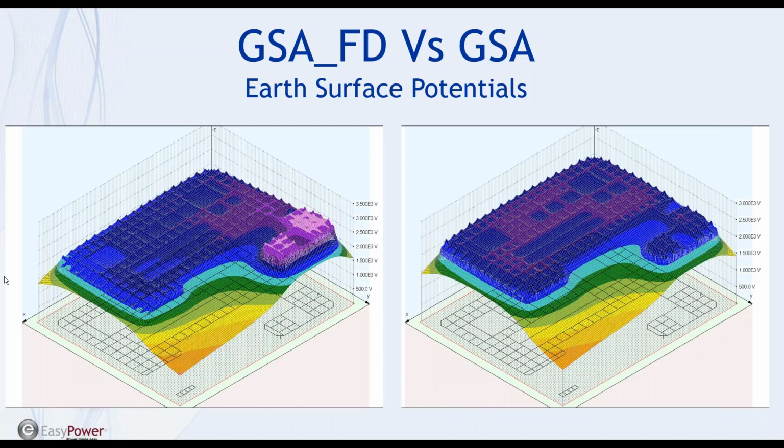XGSLab takes into account self and mutual impedances and also the propagation effects. This is the only way to ensure an excellent calculation accuracy in case of large grounding systems, soils with a low resistivity or high frequency applications.